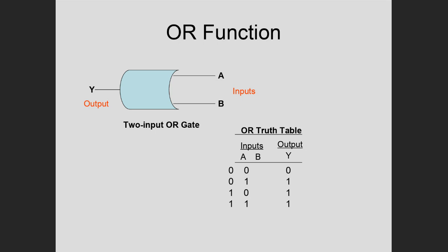And this is the OR gate. Now, in the PowerPoint, when I drew this OR gate, where the Y output is, there's usually more of a point right there. It looks like a Star Trek sign, if you know what that looks like. But this is the closest I can get to it. So if you draw it like this, I'll know what you mean. So again, you have the gate symbol for the OR, and then you have the truth table, which we've already talked about. For OR, you only need one true condition or one closed switch to get an output.